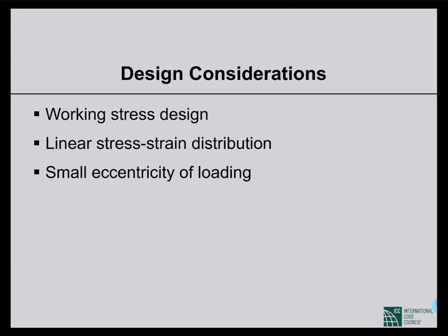So, naturally, the stress strain relationship that is considered is linear, and second order effects are not considered. That is, the eccentricity is considered to be very small, and there are provisions which try to make sure that there is very small eccentricity of loading on the wall.